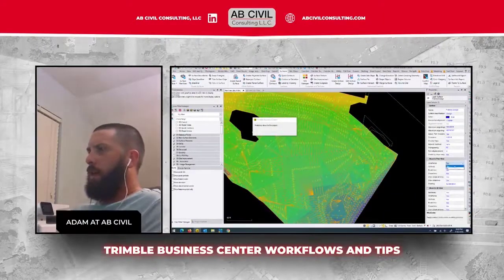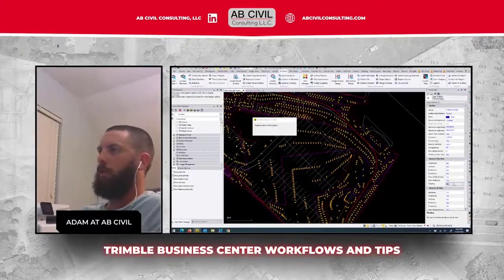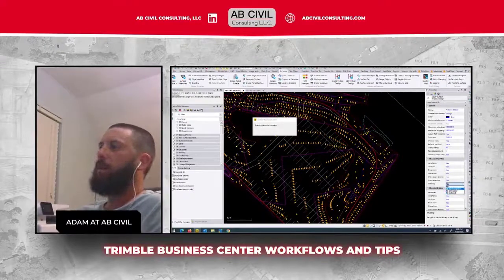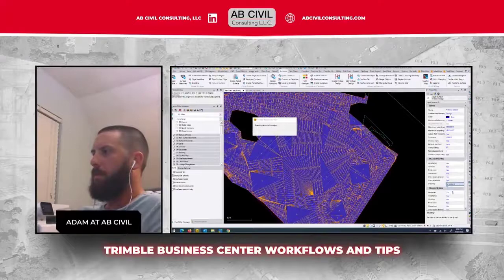So I like to turn that off if I use the elevation gradient. Right down here in plan view it says shading. You can do no, which is most surfaces that you see, just wireframe. You can do by elevation, by surface color, and by material. Surface color, of course, is just whatever the surface color is. But the last option right here, by elevation,